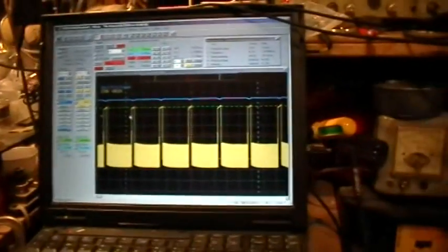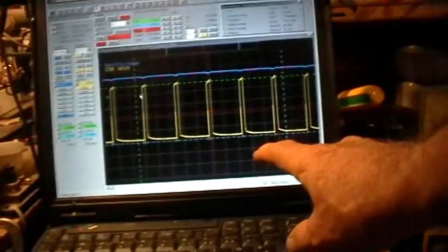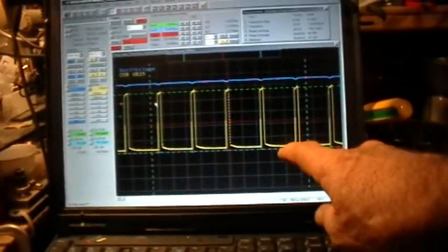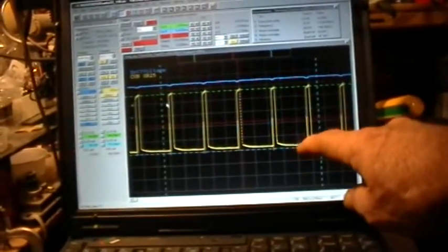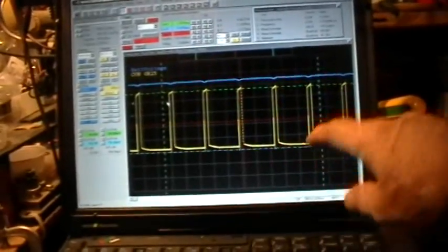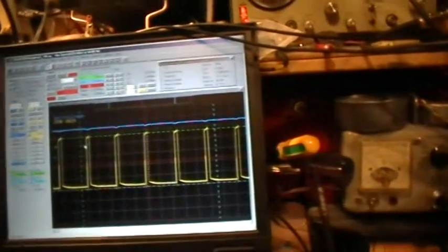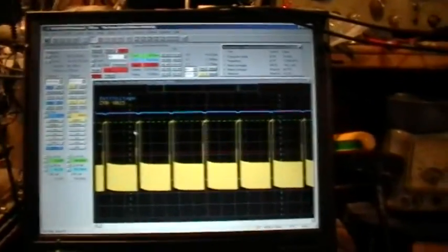And now again, if I put the jumper on the board to actuate the snubbing circuit, you can see that the oscillations go away and that there is a little bit of positive current even during the times where we would normally be seeing the oscillations there. So the oscillation mode does contribute some real current to the load, but it has no other benefit.